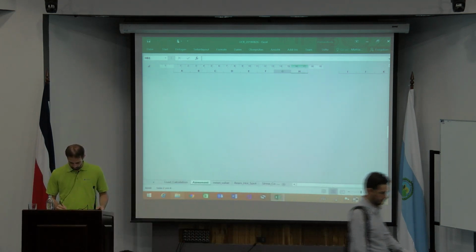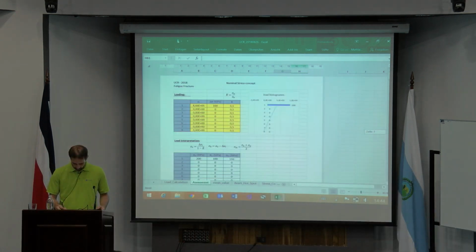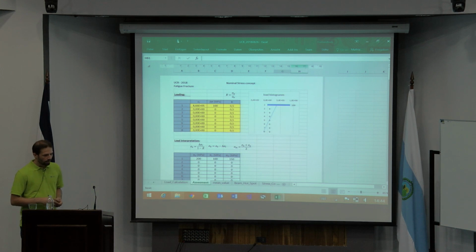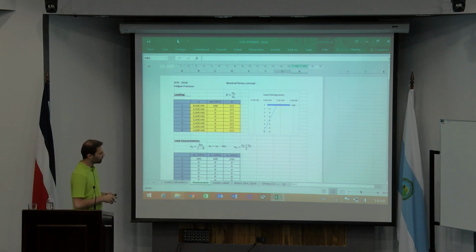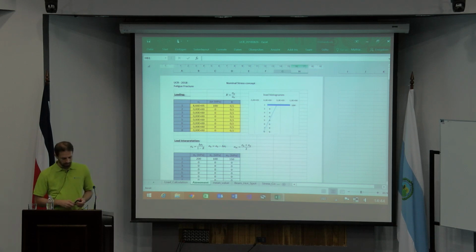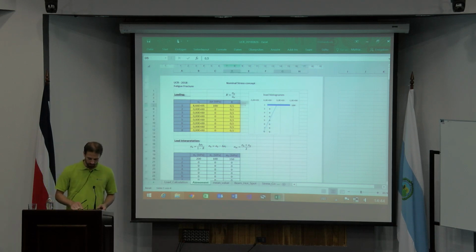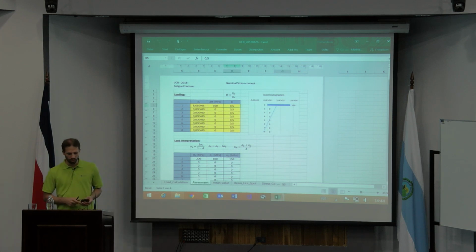So what I want to focus on today at first is the importance of the mean value assessment. Because this one is always, I was also looking at this yesterday, and as you can see here, the mean value is always related to the stress ratio, regarding the recommendations or the guidelines you usually have in the fatigue assessment.